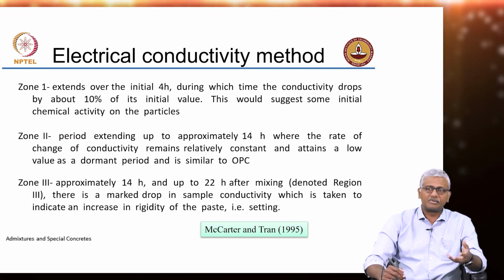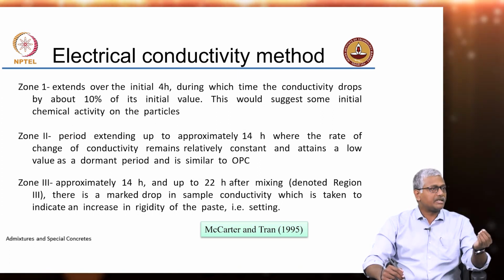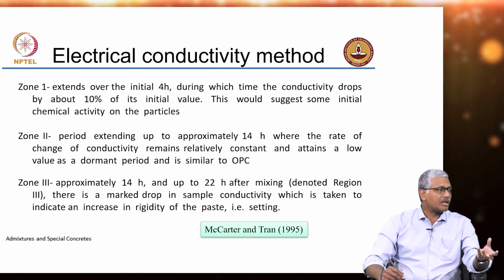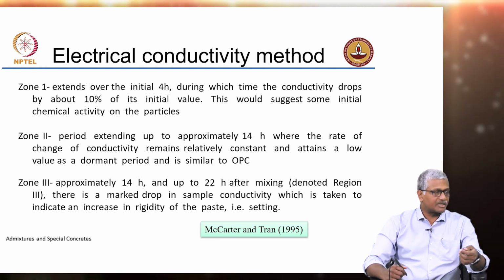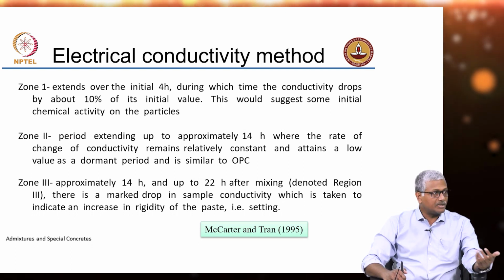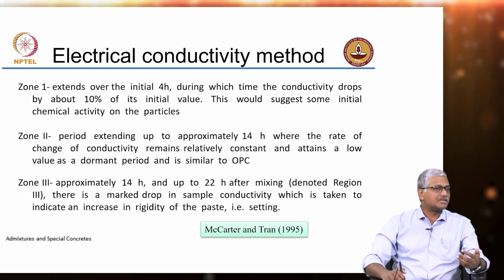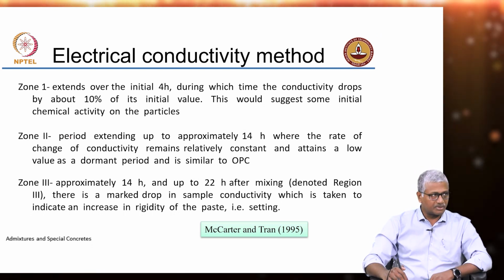See, this is quite similar to your heat evolution in cement pastes, right. There is an initial heat burst because of very quick reaction on the surface of the particles, but after that the reaction slows down significantly. Similarly, here pozzolanic reaction also in stage 2 is nearly non-existent, or it is happening at a very low rate. So, you cannot really see the change in conductivity.